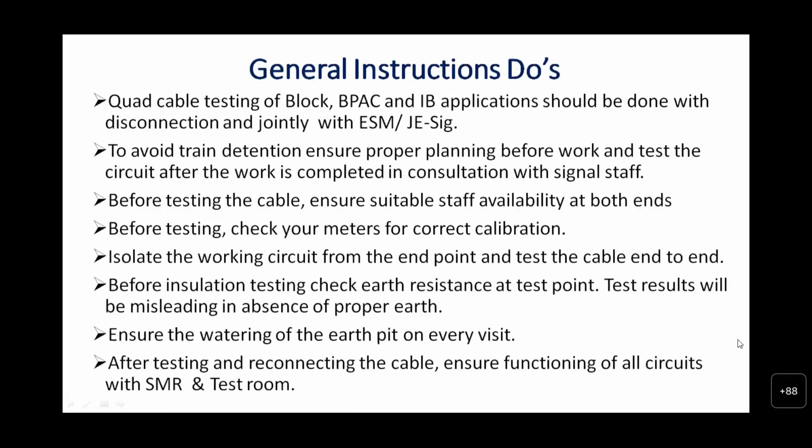General instruction, do's. Quad cable testing of block, BPSC and IB application should be done with a disconnection and jointly with ESM or JE signal. To avoid train detention, ensure proper planning before work and test the circuits after work is completed in consultation with the signaling staff.